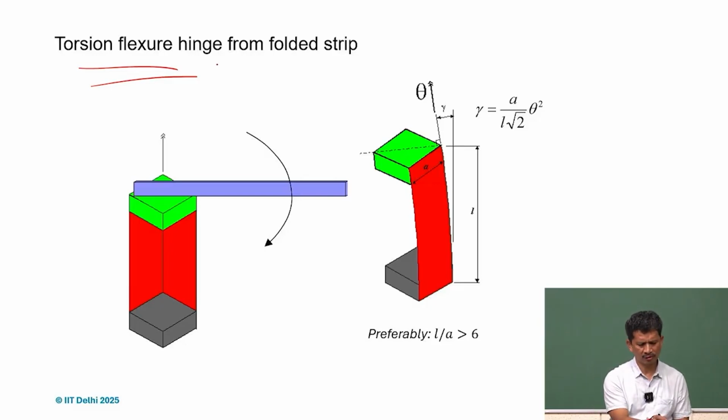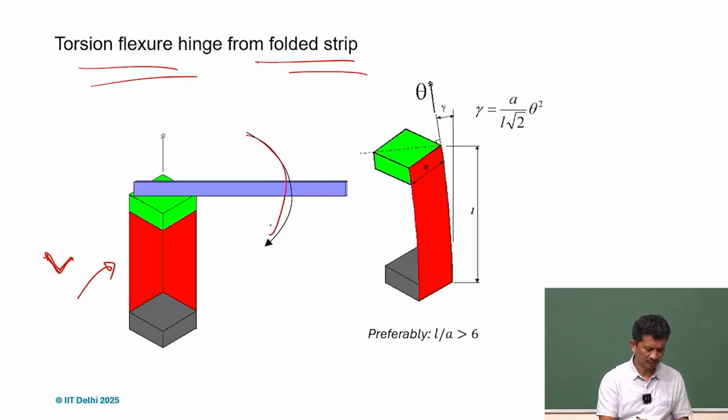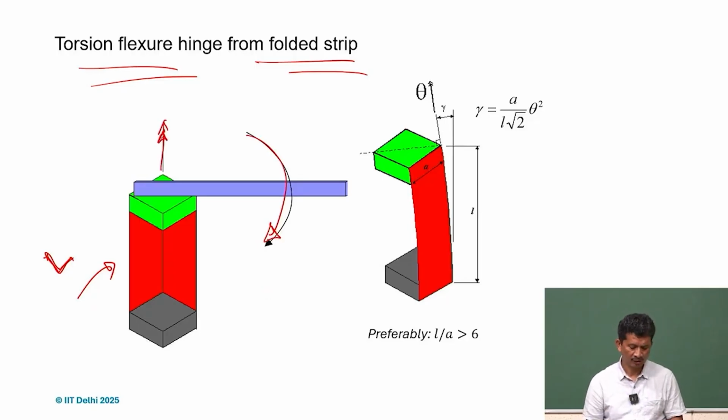Again, the collar hinge is an L strip, an L section, and by now you know that if you twist it, you can turn it. If you place it and apply a torque here, you can get this rotation. What is important to understand is that when you try to rotate, the rotation axis will be the fold axis where the two planes intersect.